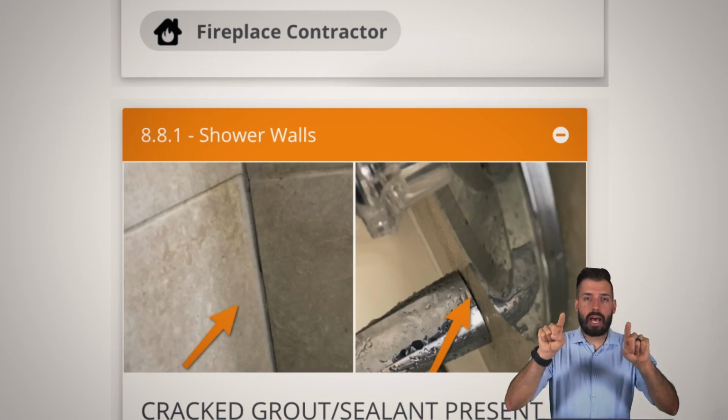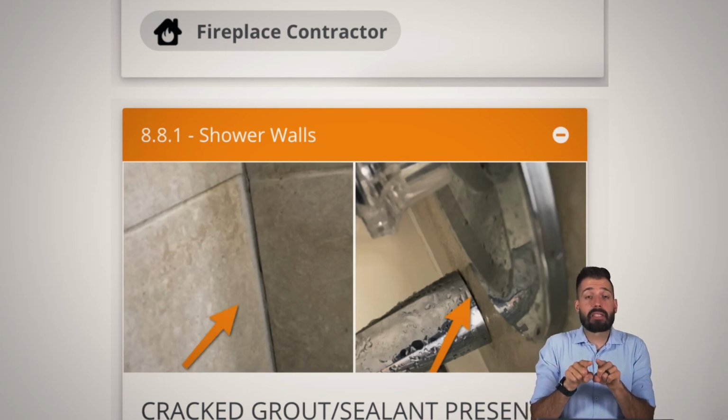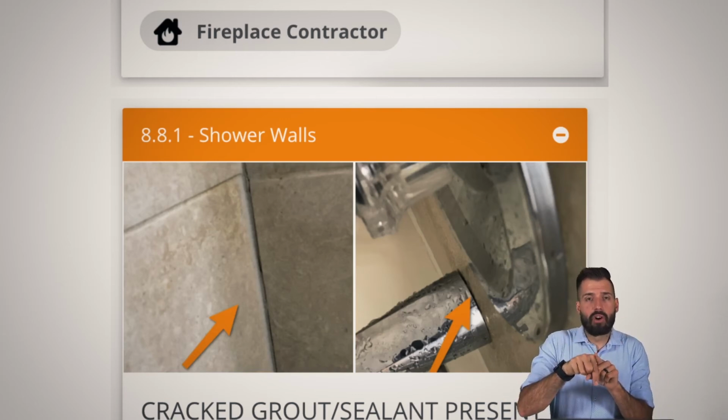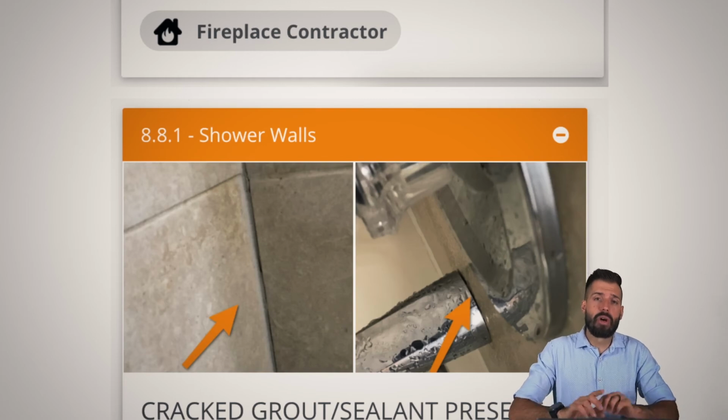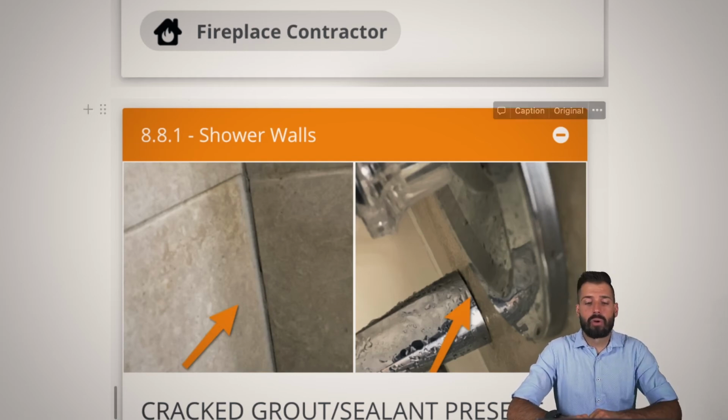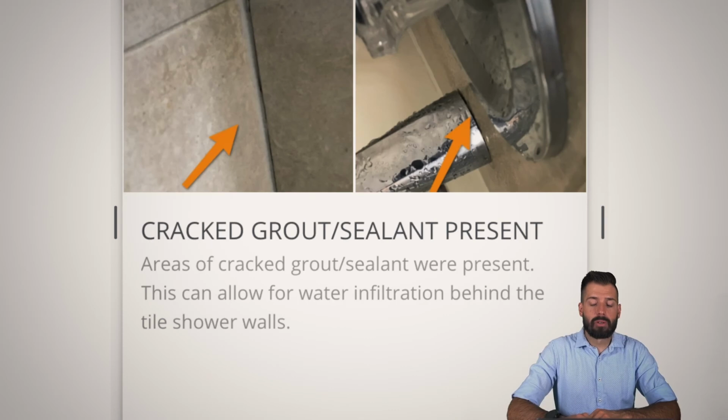We just want to go from the top and then get about 90%, because if water does get down there, we don't want it to just fill up and then damage our wall. We want it to be able to come out that little opening and back into the shower area. So you want to just wrap that about 90%, leave a little bit of space for water to come back out if it were to get trapped back there. And same thing with the corners. You just want to fill in the corners to make sure that water doesn't go where it's not supposed to.